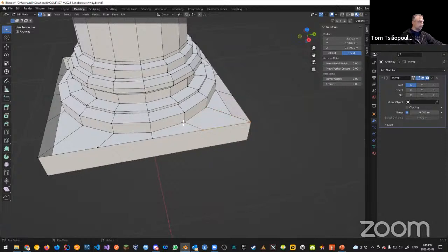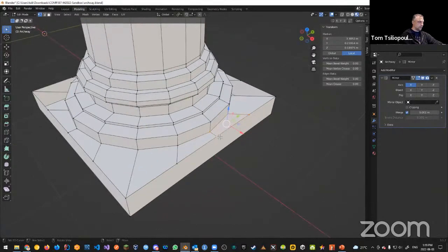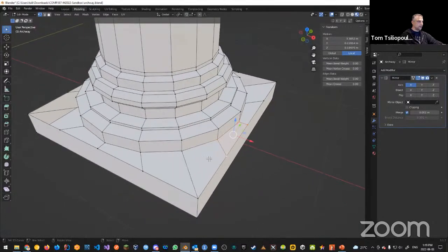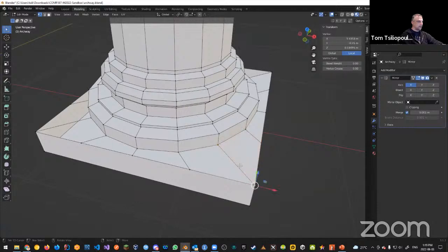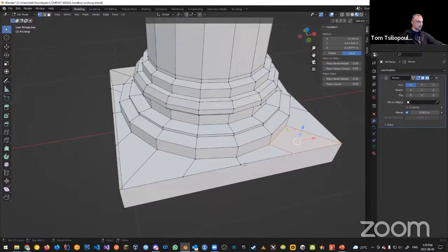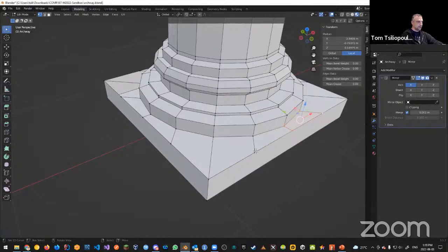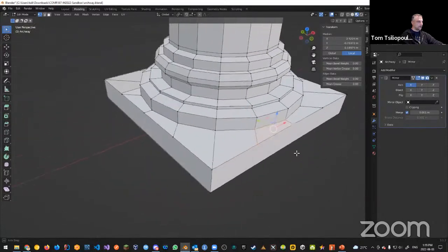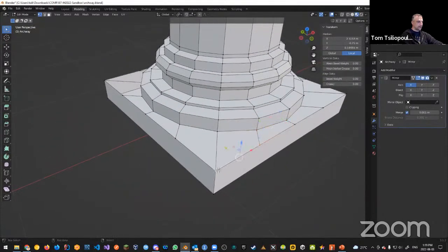And then you want to do the same thing with these ones. Now you could have fast-tracked this and done it from the beginning, but I'm doing it this way to show you how to create faces, maybe remind you how to do that. Again, I'm getting all these 4 verts. Once I get these 4 vertices, press the F key, and then you create your face. Make sure you don't select other vertices by accident. All right, so again, I've got these faces, and we're gonna inspect it afterwards.